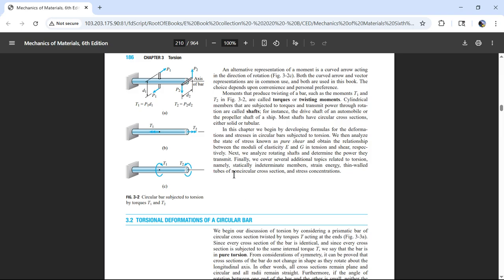If you cut that tank cross-sectionally and take all the cross-sectional area of the steel, let's say it's 100 inches squared of steel, and you're applying a force on either side of 100 pounds, you're going to get 1 psi on that tank.